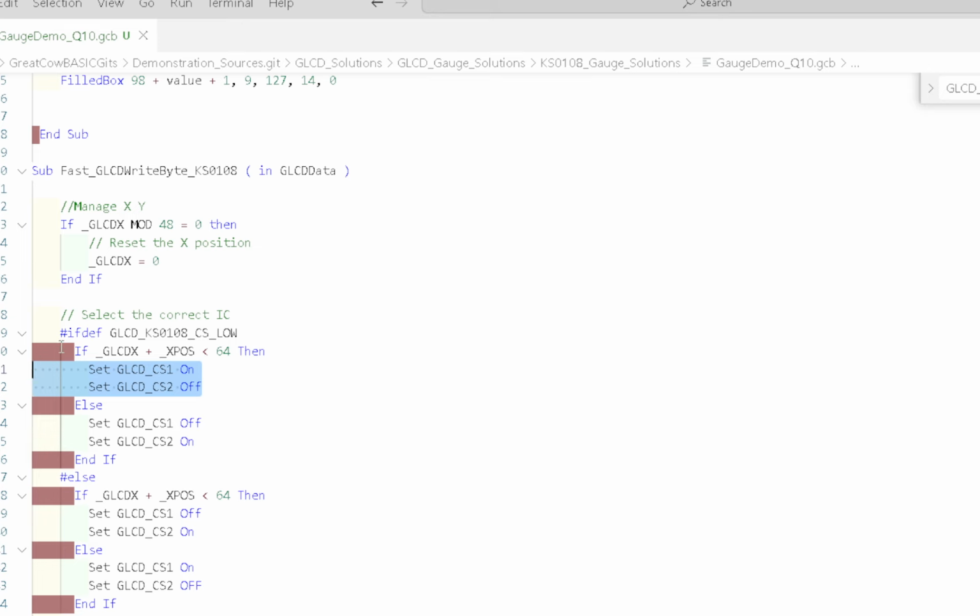So now I've got a new constant to control these new GLCDs. And these new GLCDs, the actual integrated circuit is an SLG12864, not a KS0108. It operates almost the same, okay, but it's not exactly the same. It's not perfectly the same.